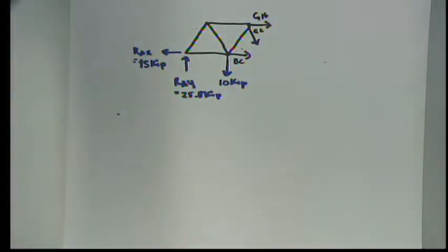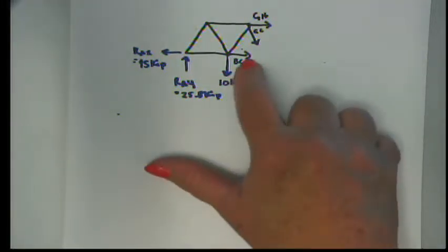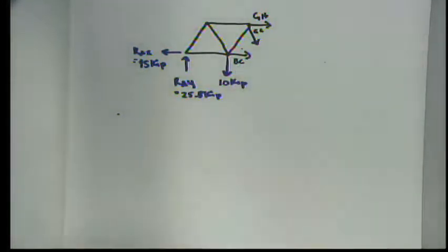Whatever structural member you want to get the tension or compression in, you cut that one, and then you cut whatever else you have to cut in order to have a section that separates like this. I'm just going to do like an A to A GH through point C. Oh, well, it's not really going to matter. I mean, it seems like it would, but if you go through point C, you just want to make sure that you're going to do either one side of point C or the other. But yes, you could do it that way if you wanted to, so that you wouldn't be cutting BC, that you would be cutting CD instead.